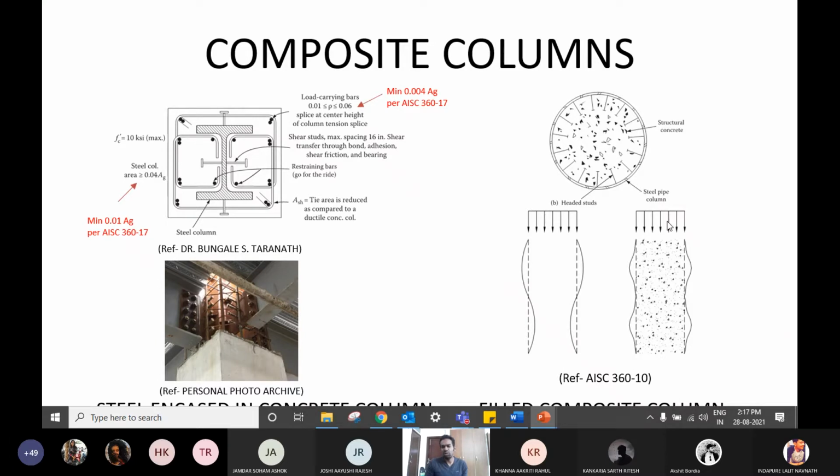Now how do you escape from it? You need to design your sizes, and you might have to increase your wall thickness, the steel wall thickness, so that it doesn't buckle for the kind of load your building is putting in, right? You estimate the load, how much is going to come up, and you check if the steel wall is going to buckle or not, and that's how you check it. You make it thicker, or else you see,